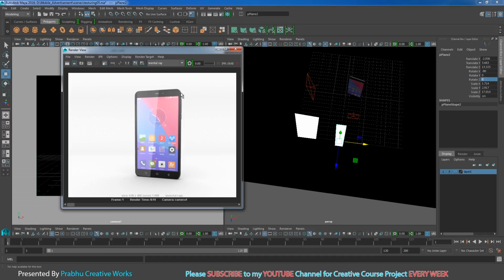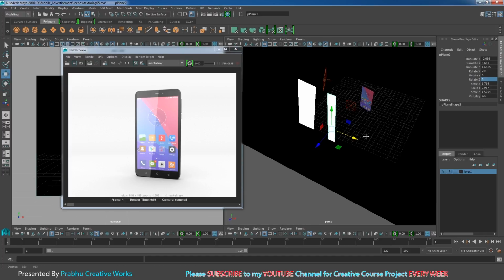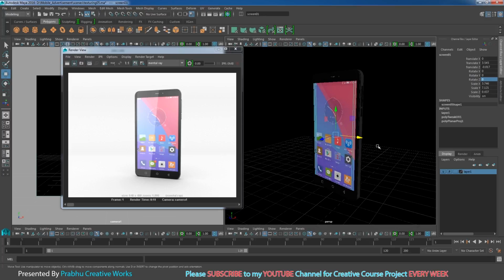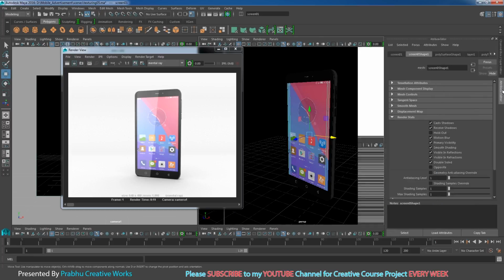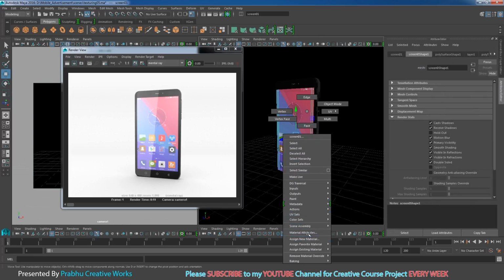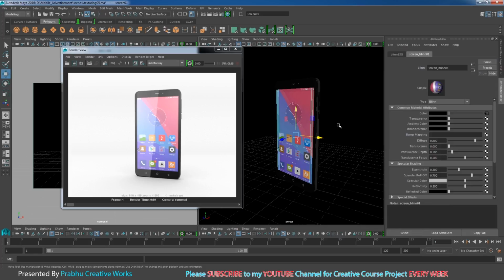Okay, so now it adds a perfect reflection for this corner. So this is our final lighting for our scene. Before that, I want to reduce this screen intensity a little bit. So I will select my screen, go to attribute editor, right click and choose material attributes for your screen.